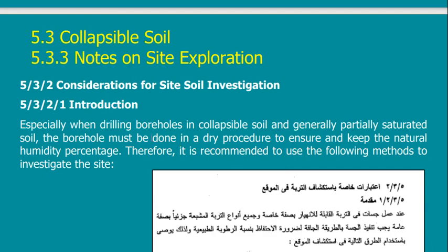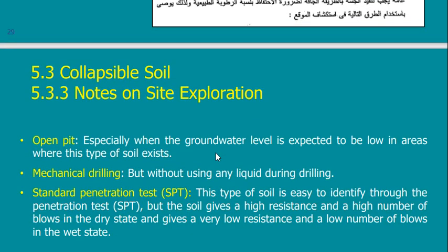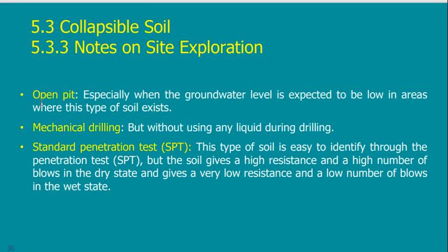We said that it is better to take samples that have the normal water content of this soil. So the methods that we can use for site investigation are either open pits, where we don't use water, or mechanical drilling but using air cooling instead of a liquid cooling system, or to do testing for the soil in place and do it maybe twice.